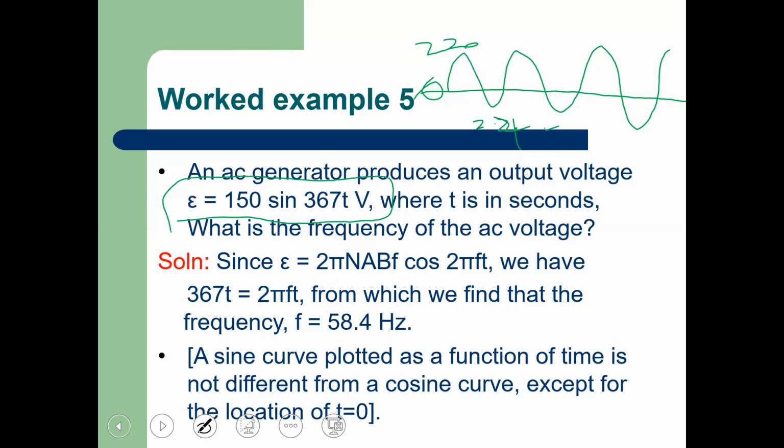But after every period, like you said from NEPA, it's 50 Hertz. When we say 50 Hertz, what is the period? That's 1/50 second, right? So every 1/50 second, a complete cycle is made. And what you will have at 1/50, 2/50, 3/50 should be the same if you move along our sine wave.